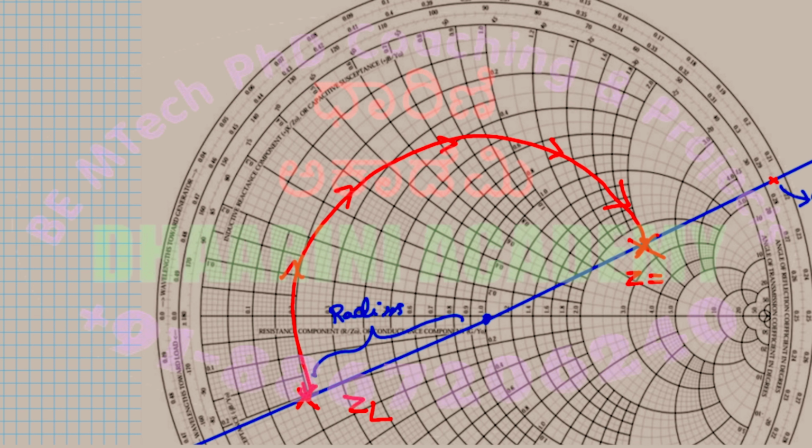2.2. Perfect. All right. So that's 2.2 plus j, I think you told 2.5 or something, I guess. Right? What is the x value you get? 3.0 plus j3. All right. So that's the z value you get. That is the impedance at a distance of lambda by 4. At a distance of lambda by 4, you have impedance equal to this value.